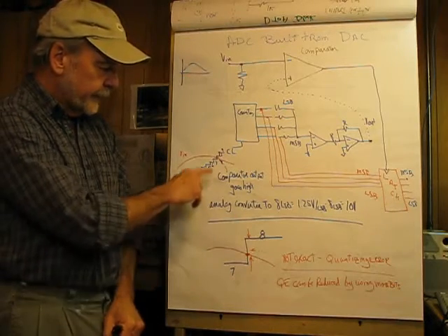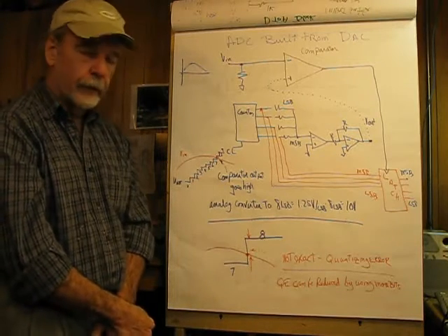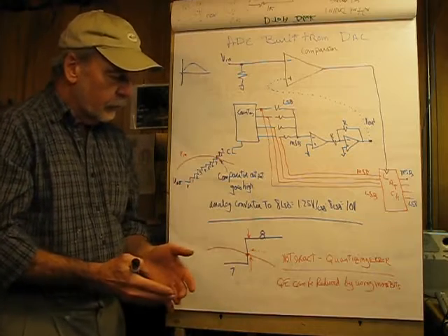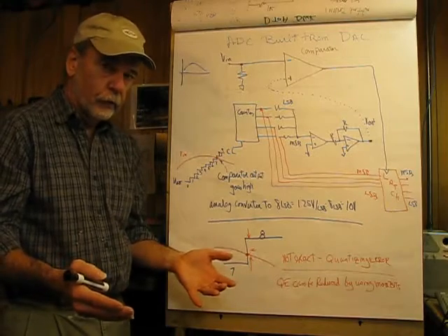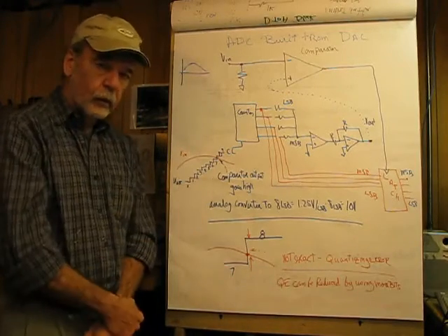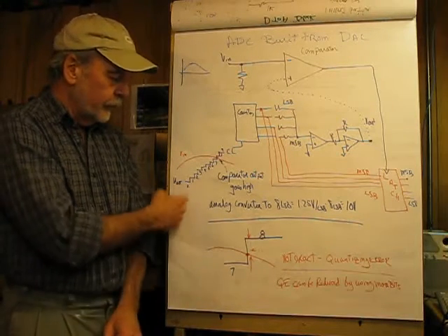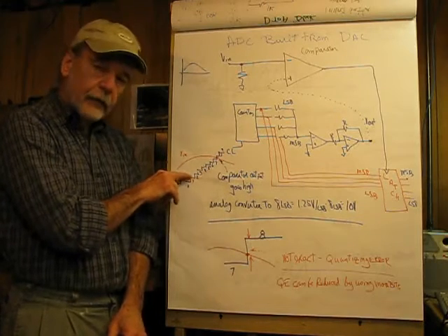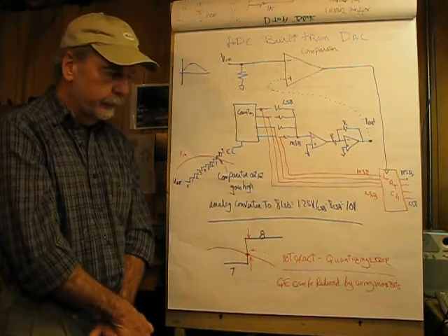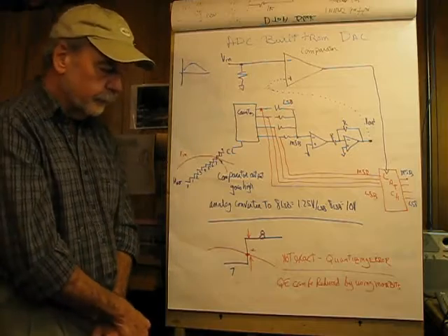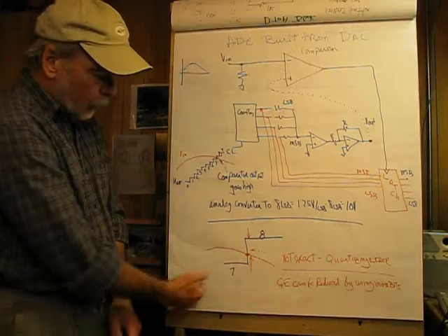The issue in here is that I'm reading in between steps. So that's called quantizing error. And in a digital system, you can't have infinite resolution. In an analog system, it is infinite resolution. So the difference between what it is and what we say it is in binary is called quantizing error. And the way we can minimize that is to use more bits, so the step sizes would be smaller. And we would reduce the error between our input and our converted digital output by doing that. And of course, there are trade-offs. It's going to cost more money probably.